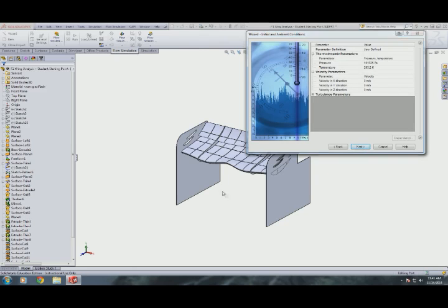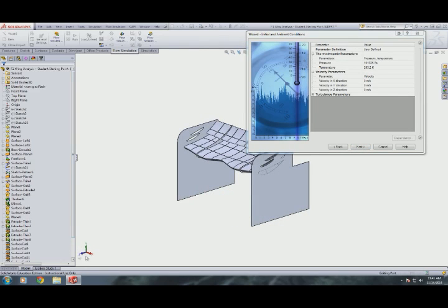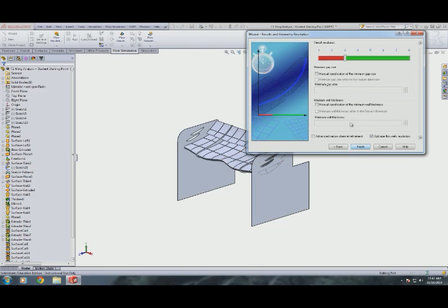You see this triad down here? The z vector is pointing the way we want to go. So I think peak speed on these F1 cars is around 220 miles per hour, and in those units this translates to 102 meters per second, which is what the homework says to set it up as. Interestingly enough, I just made a mistake. You have to have negative 102, because if it's positive 102, it's going to be flowing in the z direction, so your wing will be going backwards, which they don't work as well going that way. Standard temperature and pressure is fine there, so we'll just leave the grid normal for the moment.